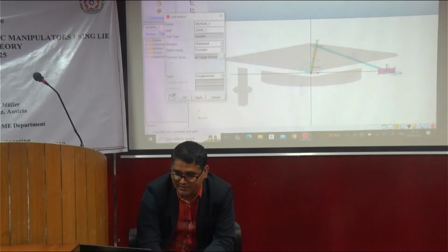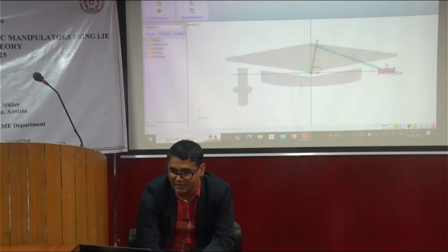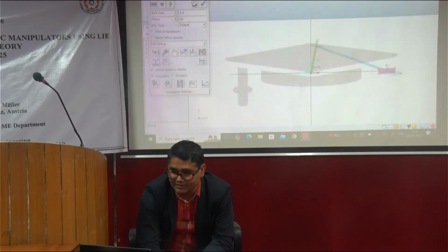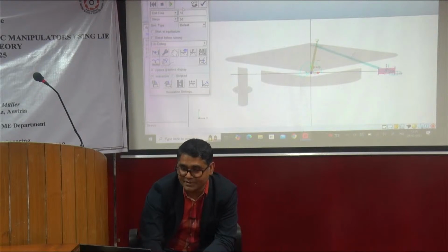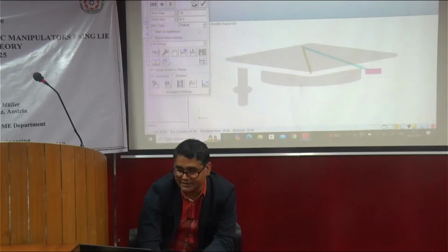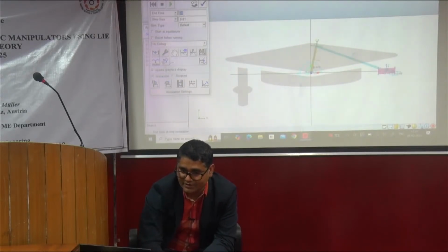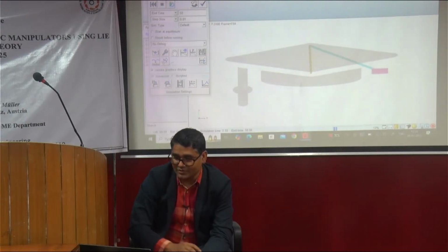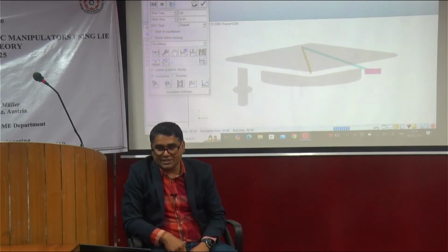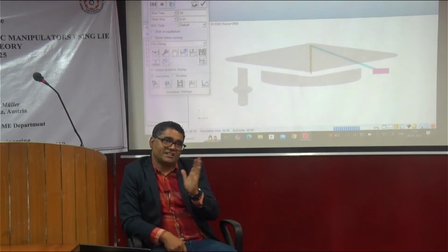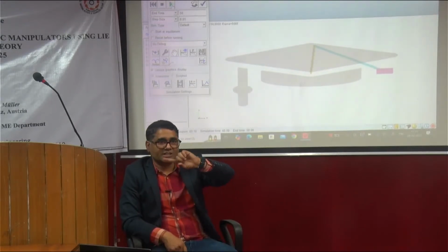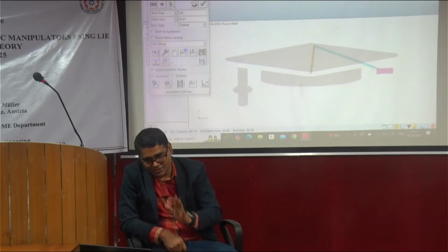So that I have to provide. Now I have given it, I can go to simulation and check the simulation here. I will make it 10 steps, and the step size is just 0.1. Let's run. I want to see it a little lower, and this one is 50 seconds. If I run, you can see this mechanism is rotating only 30 degree into sine time. So 30 degree will rotate in sine time. This is the function that is happening.